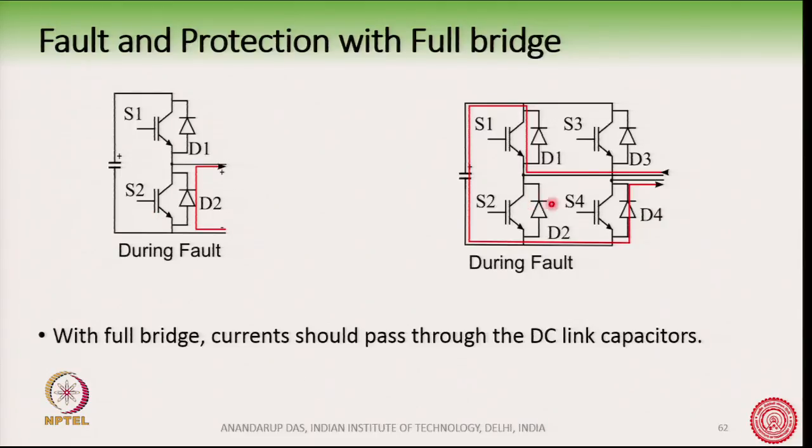In case of a full bridge, when you turn off the transistors here, then also this full bridge will act as an uncontrolled rectifier.